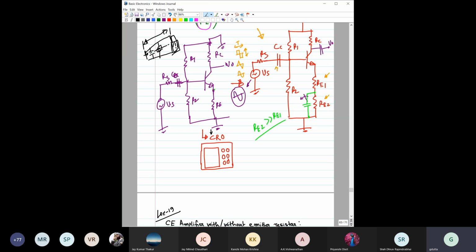Because a cathode ray has to have an electron gun, then high voltage accessories, then the deflecting plates. Then you also have to have some amount of distance, so that from this cathode ray you should be able to scan from the top of the screen to the bottom, as well as from left to right. So it should have some particular length, and that is why earlier televisions used to be quite thick. But now consider LCDs and this type of televisions, there it is very thin compared to the earlier televisions.